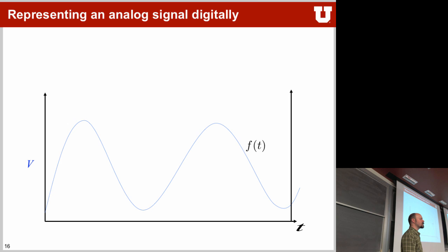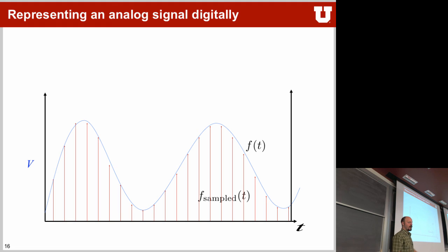Assume we have this signal here, f of t, that changes over time. What we have to do is sample it over time at a certain rate Ts. That's kind of what we did before with the logic analyzer. We told it to sample at 1 divided by 40 megahertz. That will give us all these different samples. These samples will tell us approximately what the form of this signal looks like. It gives us these little dots here in digital counts. And then we can use formulas to find out again what the actual unit was before.